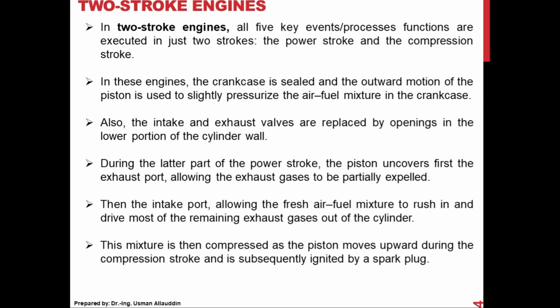When we reach the top dead center, the piston will again go back to the bottom dead center, but during this process the exhaust valve will be closed and the inlet valve will be open, so the air-fuel mixture will come into the cylinder. These are the five key events or processes: compression, ignition, power stroke, exhaust, and intake. And we have distinct strokes for each process.